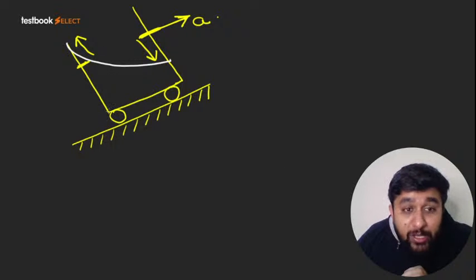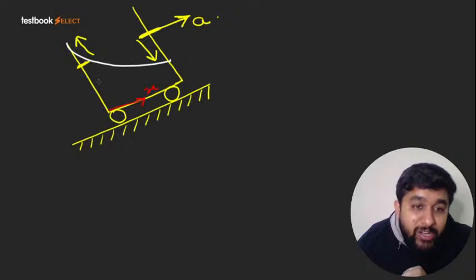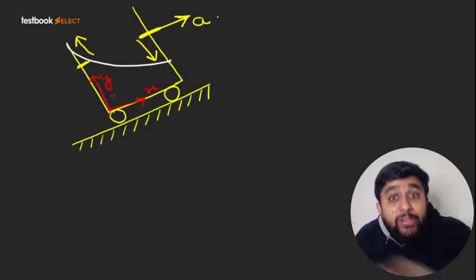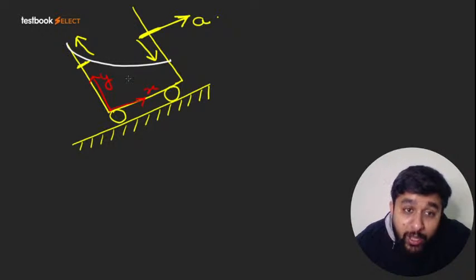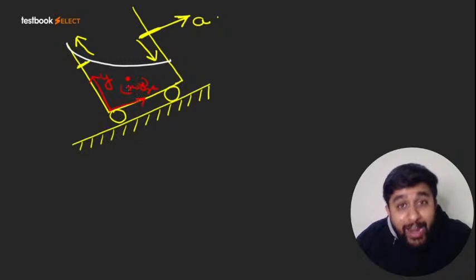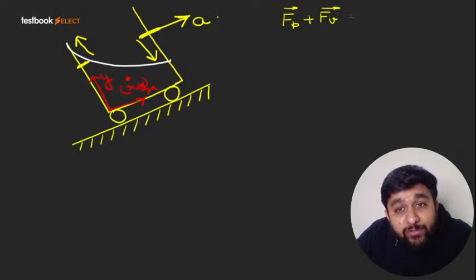Standard procedure है कि भैया just take one direction as x and the other direction as y. Let me take the inclined direction as x because the container is moving along x. Now you take a point whose coordinates are x, y. At this point there will be a fluid particle. So for the fluid particle, when you write down Newton's second law of motion, that is Euler's equation, you will say the resultant pressure force plus viscous force plus weight is equal to mass into acceleration.